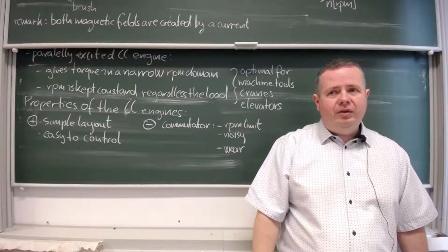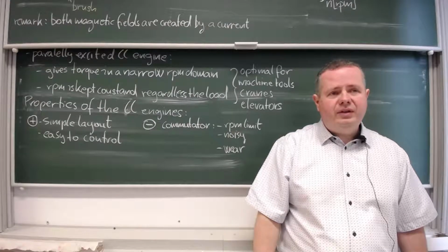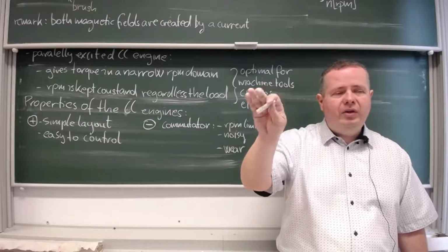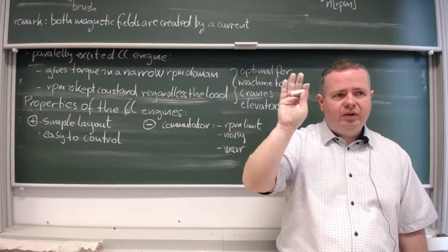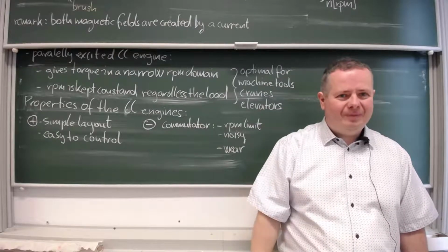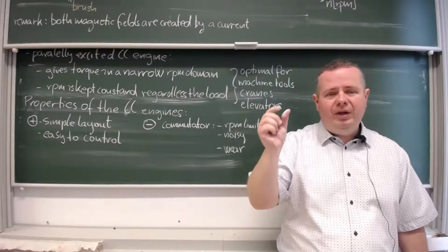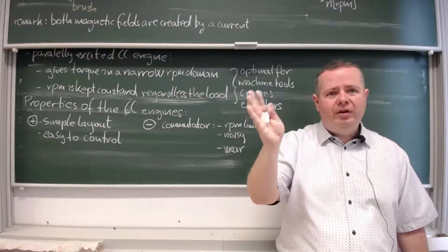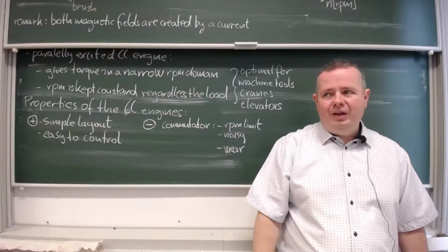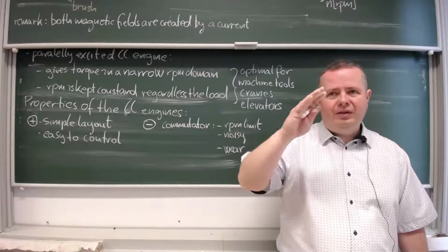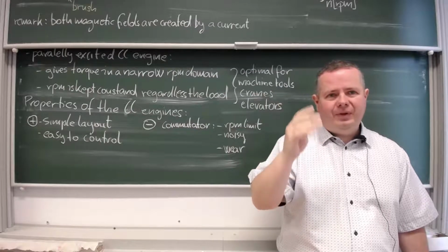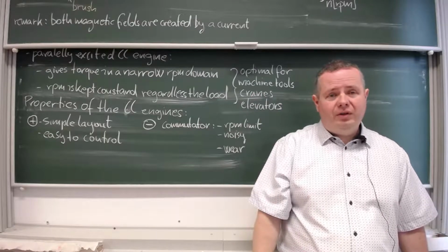But it has also the consequence that when you are cutting the small layers from the carbon brush, the carbon powder is accumulating in these gaps. And soon it makes conduction between the neighbor wire ends. And once you get longer and longer conduction between wire ends, it will short circuit your rotor.